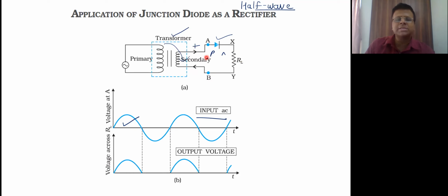And forward biased condition, we know that you are going to have a current on the output. So your PN junction acts like a short circuit. It's a complete short circuit. There is a free flow of current, and that short circuit is what I am representing in terms of the voltage across the RL here. Okay, so current will flow through the load resistance, and the way the input voltage is going to vary, the current will also increase accordingly, and the voltage across the load will also increase accordingly, like this.